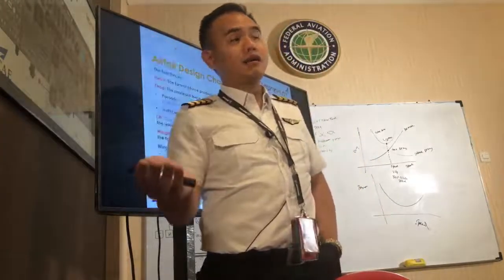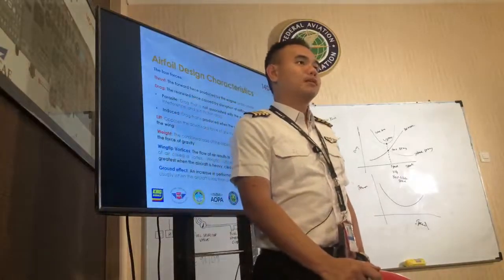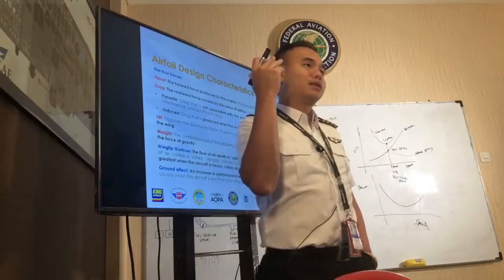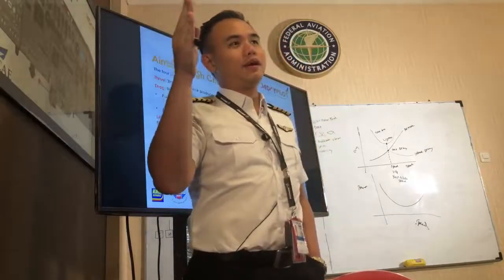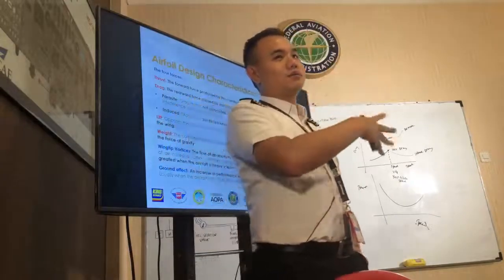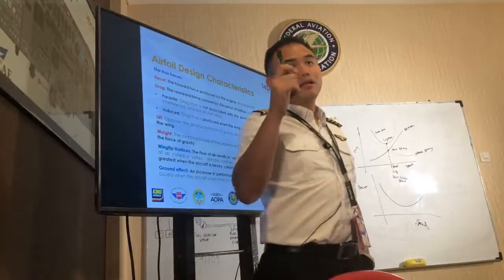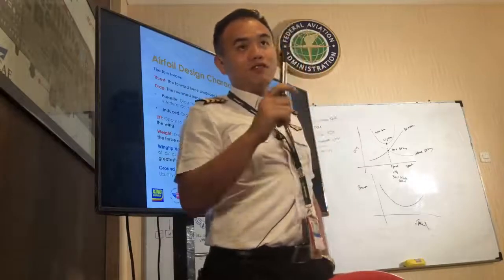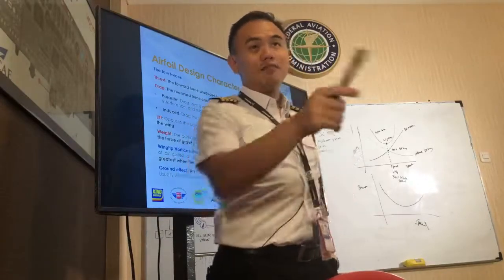How about in the car, if you want to reduce your speed, what are you going to do? Just push the brake, or just release the pedal. Then it's decreasing, like 50 mph, 40, 30, 20, boom. But in the airplane, wait a second. At a certain speed, if you want to fly at really slow airspeed, you have to add power.